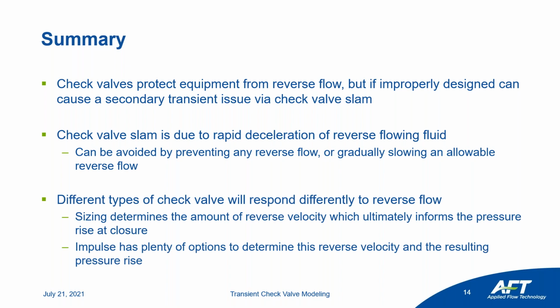There's a lot of considerations with the construction of the check valve and the different types of check valves and how that's going to respond to different reverse flow. It also depends a lot on the deceleration aspect. So how quickly is that flow coming to a stop? And we see that in all cases as that deceleration increases, there's much more likelihood for reverse flow and therefore much higher likelihood of check valve slam.